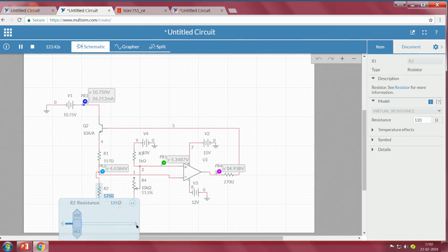So this is the intention behind rigging up this circuit, and you always want your load to be working at constant temperature. And you see how the difference between the two voltages is always being adjusted by the amplifier here and fed back to your circuit.